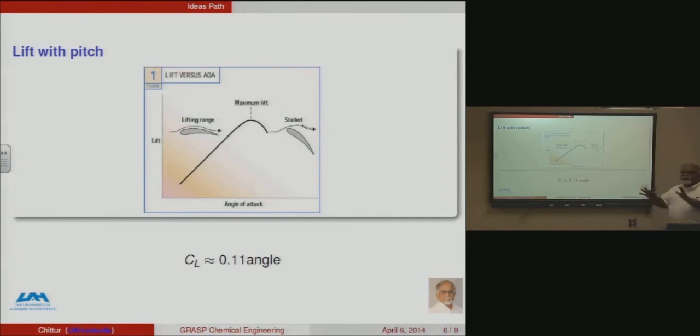So for the most part, what we're going to say is, for an angle greater than 0, the CL is given by this equation. At an angle of attack of 0, CL is approximately 0.2, something like that. You can find lots of curves like that. Okay, so this is how you calculate CL. Now we know all of the terms, which allows us to calculate the lift experienced by an airplane flying at a given altitude.